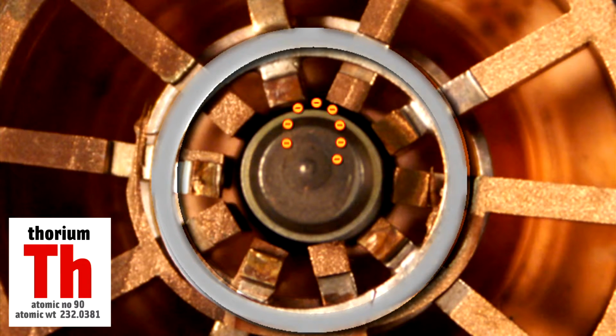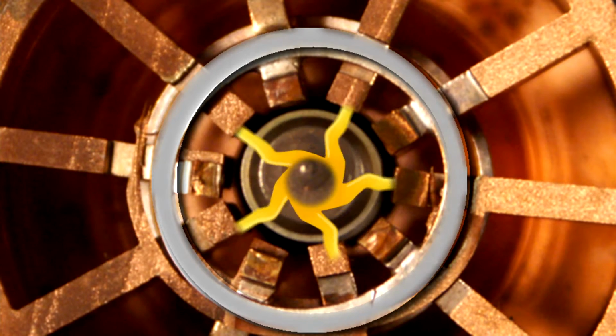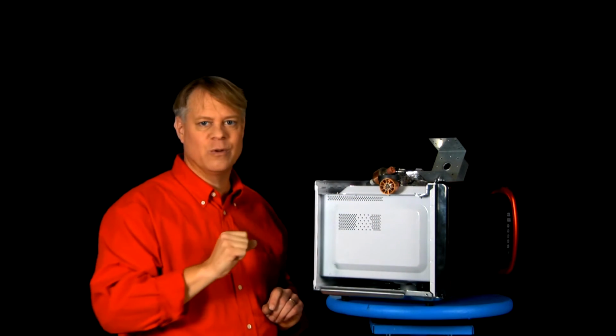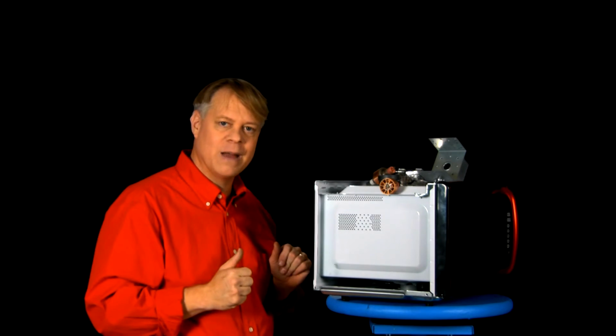We adjust the magnetic strength so that the now orbiting electrons just brush past the opening of these cavities. Like blowing over a half-filled pop bottle to make it whistle, this creates an oscillating wave, the microwave radiation that heats food. It's simply astonishing that these cavities can be made with high precision, low cost, and incredibly high reliability.